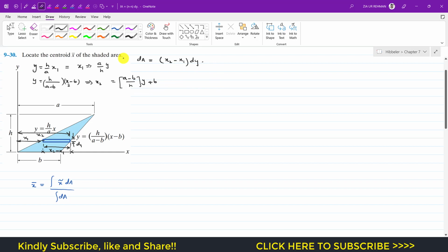So now we can write dA equals x2 minus x1 times dy. First we need to find x2 minus x1. x2 is a minus b divided by h into y plus b, minus x1, and x1 is a divided by h into y.